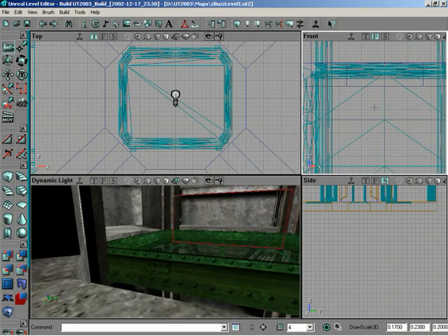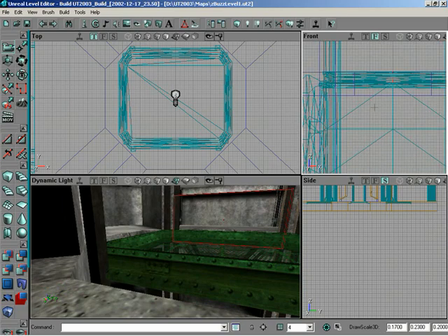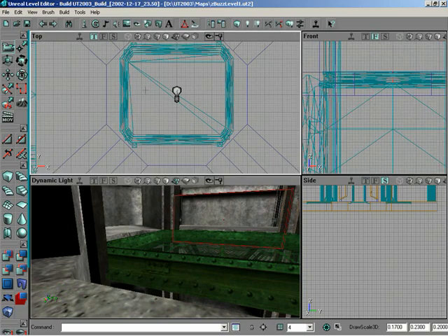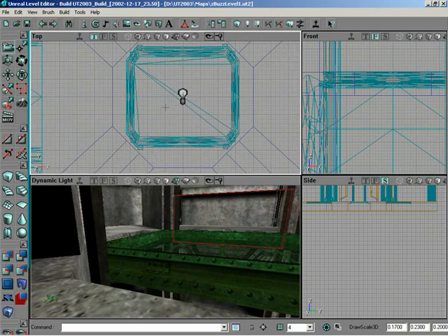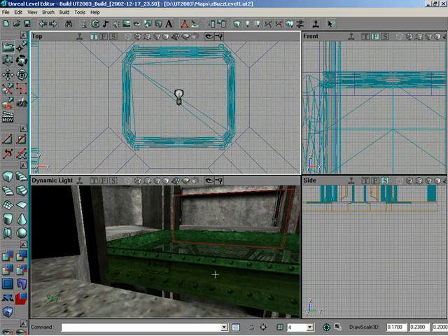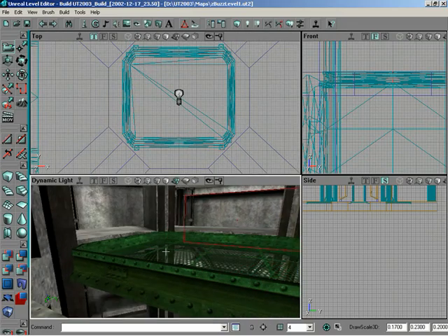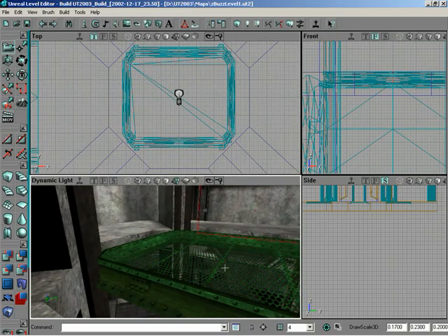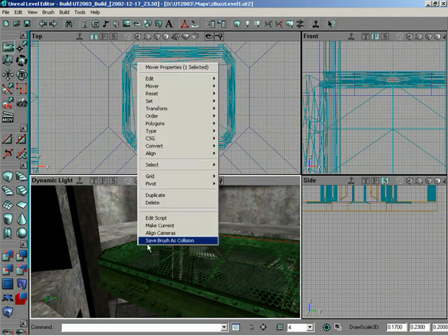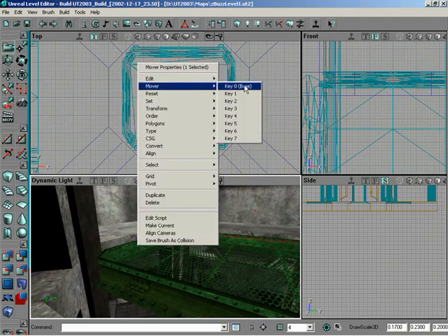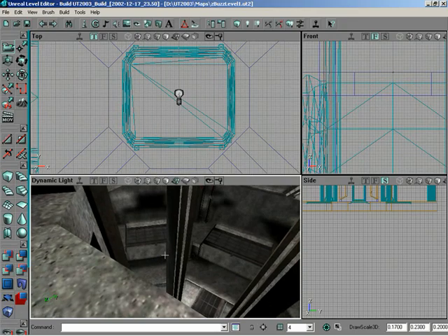Is that the same alignment that you had when it was down on the floor? What do you mean? Oh, you mean top view? Yeah, that should be right. Okay. I moved it back over some. So that's key 1, meaning that after it starts moving, this is where it's trying to move to. So let me right-click on that and make sure we set it back to key 0 before we play, so that we make sure it starts on key 0.